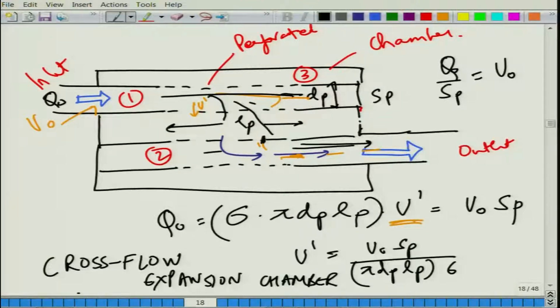Sullivan and Crocker's segmentation approach, and basically Sullivan's papers from the late 60s or probably 70s, talked about considering the gradually varying mean flow effects also. But in the analysis that we are doing, we are considering the perforate impedance to be uniform throughout the duct, and it is a distributed parameter approach as opposed to the discrete segmentation approach by Sullivan. Everything has its own benefits as well as drawbacks.